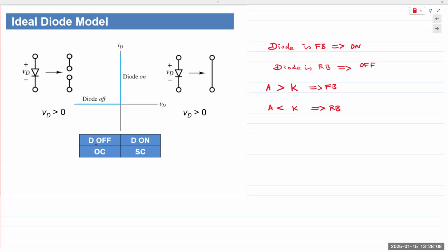This also means that the diode voltage in forward bias is positive, and the diode voltage when it's reverse biased is negative. Remember, voltage polarity is simply indicating what your point of reference is. The value of the voltage doesn't change. A couple of slides ago, when we introduced the diode characteristics, I said VD and ID.